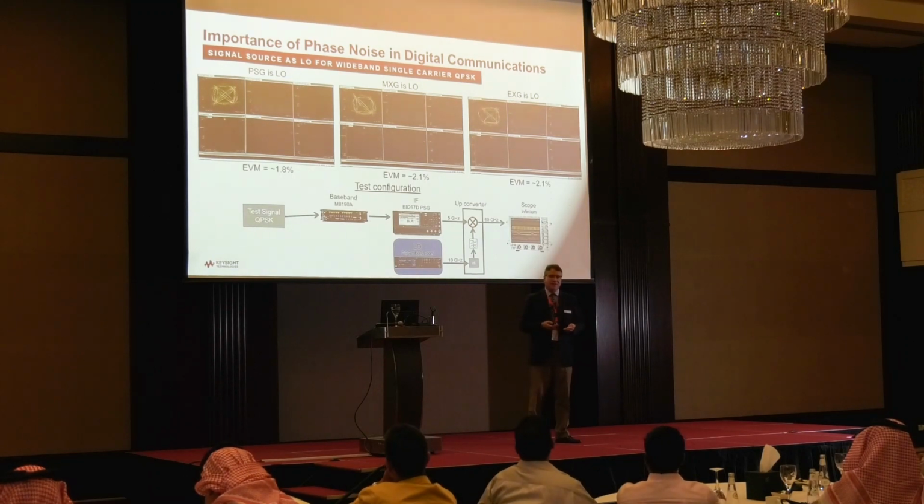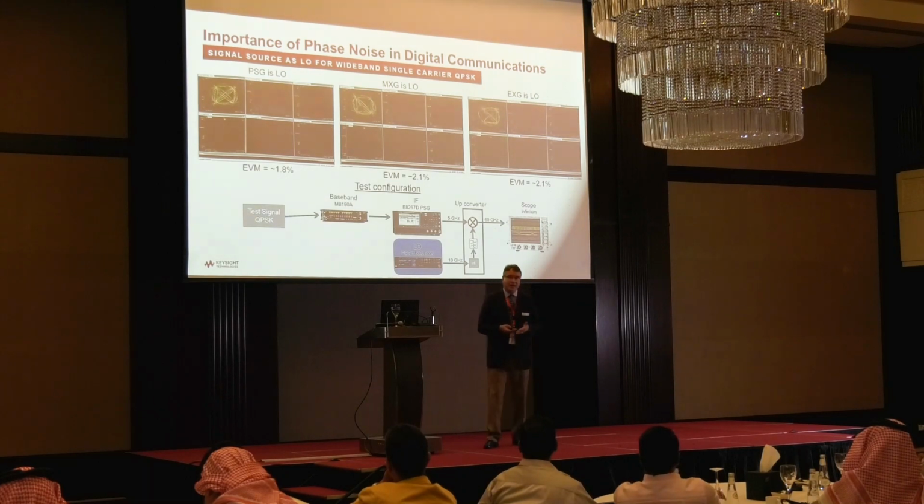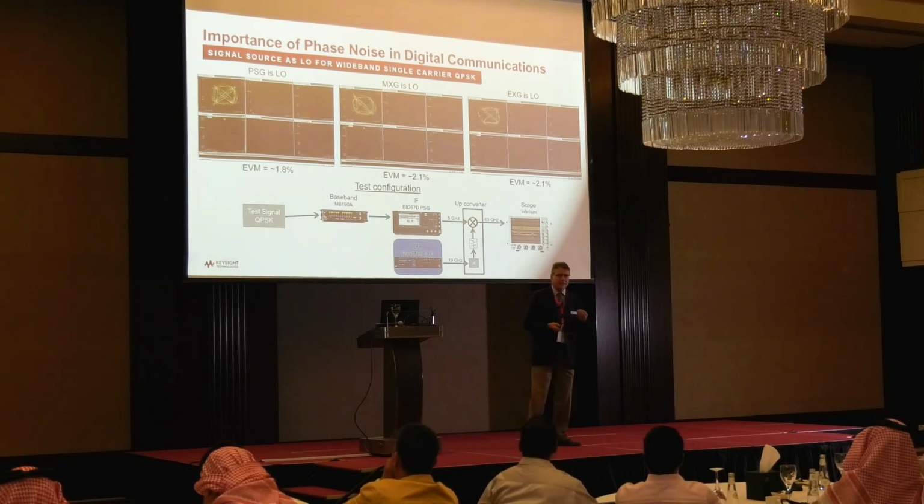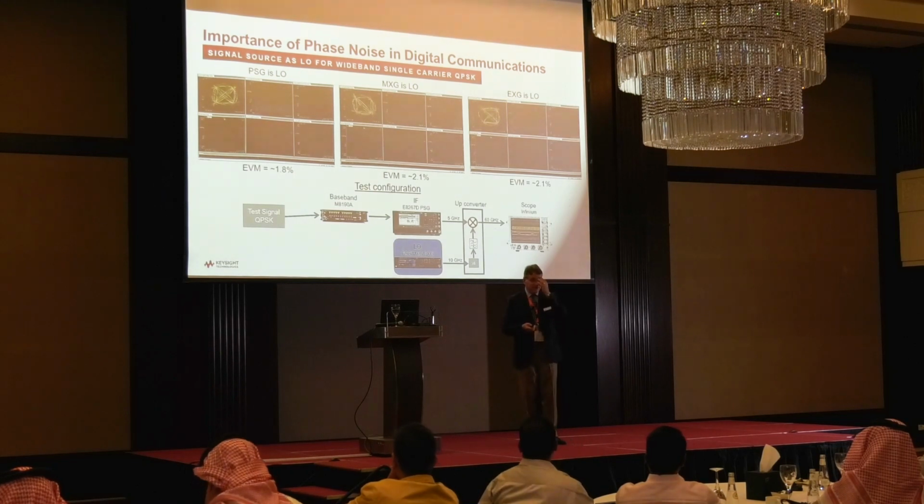Some of the more economy priced generators have slightly higher phase noise, and the EVM is slightly higher, about 2.1%. So the choice of local oscillator and its phase noise performance is an important criterion when building a digital communication system.